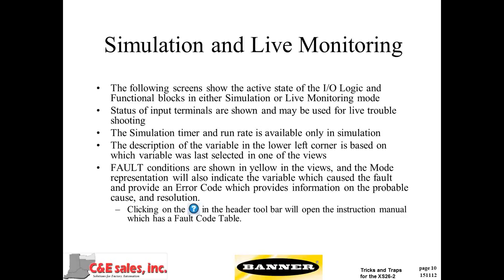One word of caution in the simulation, and I'll try to remember to do that again as we get into it, is that if you made an error in the assumption in your design, you're quite likely to make a similar error in your simulation. So remember that while simulation is a very handy tool and can look for logic errors, the final validation of your design must be done in real time. I strongly urge you to write a validation program which includes the safe way to test your system, as well as a document that says these are the results that I expect.